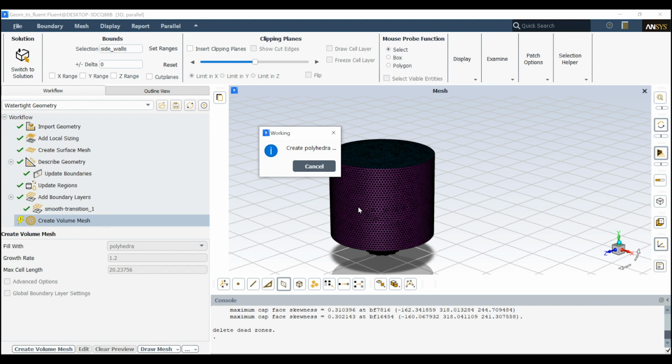You can use the mosaic shape, so you can add polyhedras near the boundaries and cubic shape meshes far from the boundary. I will try to create a video to explain those different meshing options inside ANSYS Fluent.